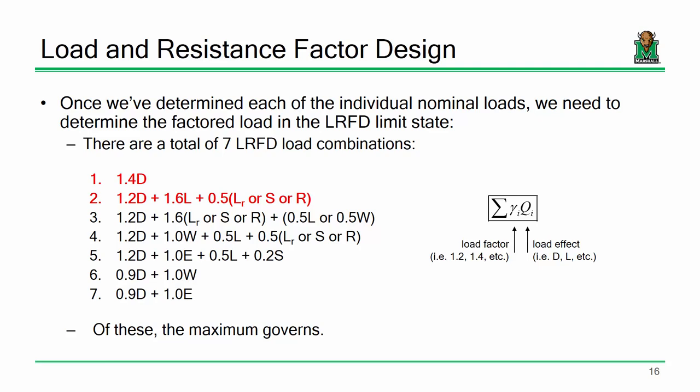If you were in concrete design, you remember some of these load combinations, like 1.2 times the dead plus 1.6 times the live. Those are the same load combinations that we're using in here. So that's a pretty nice finding. It's not new. It's also one of the good reasons why taking steel design and concrete design at the same time go hand in hand. It's not like there's a separate design philosophy in here versus in concrete design. It's the same load combos, so you're not having to remember two different ways of doing things.